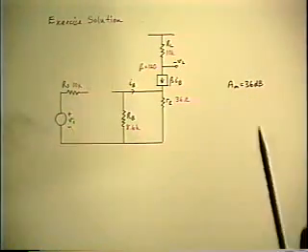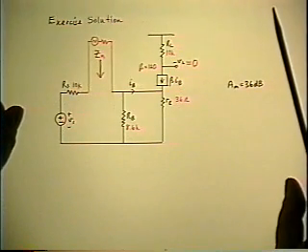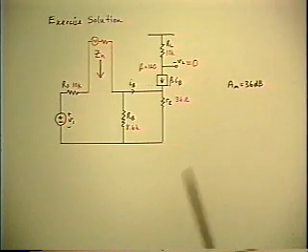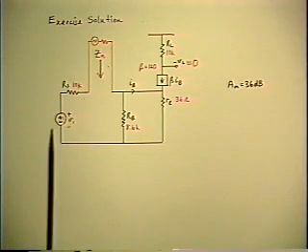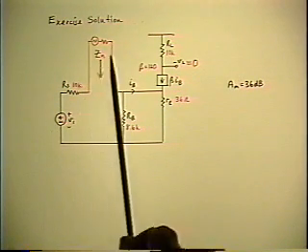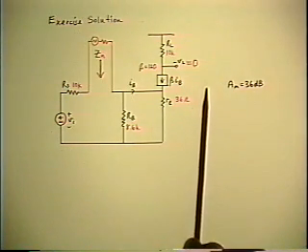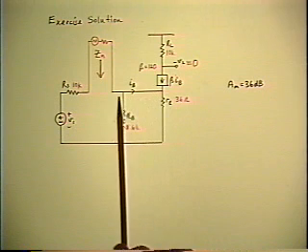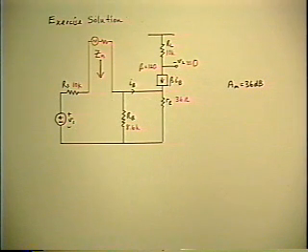Now you do the null double injection calculation. Apply a second source, restore the first source. Double injection. Imagine that the two sources are twiddled to null the output. Propagate the null back to the second source and see what happens to the current that comes from the second source, and that tells you what Zn is.